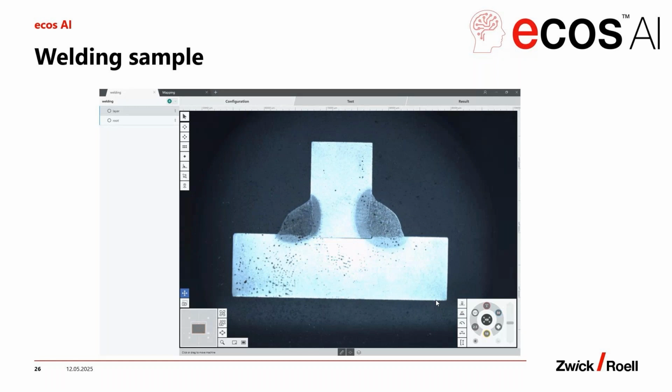And when it comes to welds, you have to etch the surface in order to see the different zones of a weld and to do the hardness testing as it's supposed to be. And etching makes the surface worse, making it harder to get a good indent evaluation. So in this case, it's something you have to deal with. What you can see here is a picture taken with the overview camera of our DuraScan micro hardness tester, where you can see the etched zones.